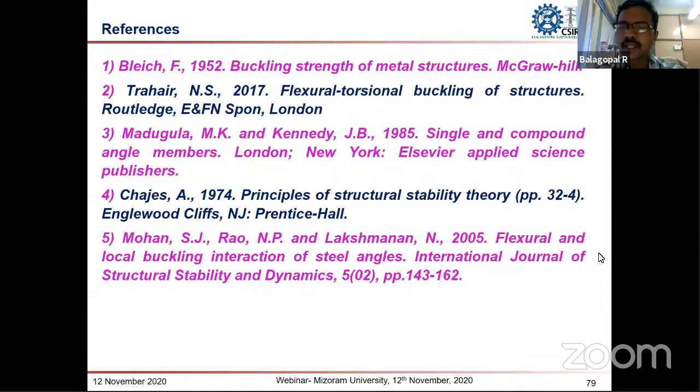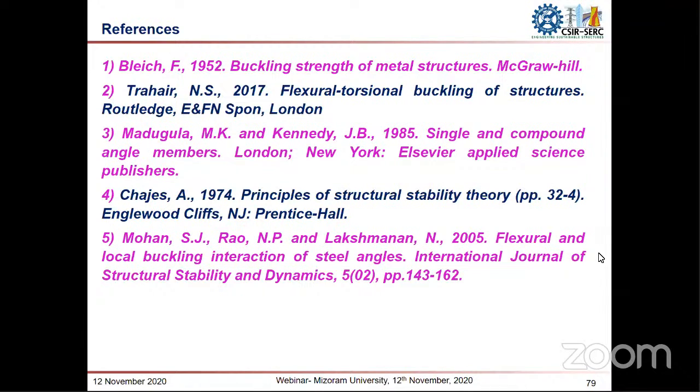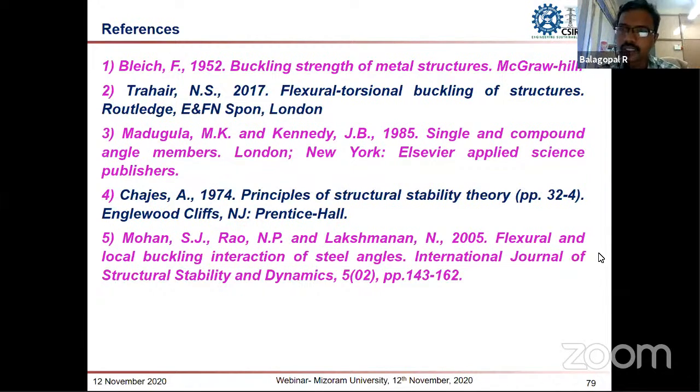Thermal stresses, no, that parameters are given for the conductors, where they have given how, in transmission towers, to account for the thermal stresses. Those parameters are given in the sag tension calculation of the conductors. Suppose if a high temperature is there, what will be the sag and what will be the influence of that high temperature on the tension load on the tower, and also if extremely low temperature, if there is ice accretion on the conductors. Those parameters are given in the CBIP manual, on how to take these temperature effects into account in the load calculation.